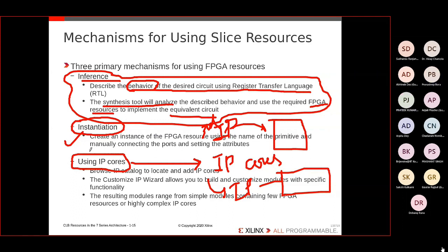Once again, sir. So as of now, what we have done is inference. What does inference mean? I have written a code as per the behavior of the resources, and the synthesis tool inferred, that means the synthesis tool understood, according to the behavior of the Verilog or VHDL language, the RTL language, that I have created this particular circuit. This is called inference.